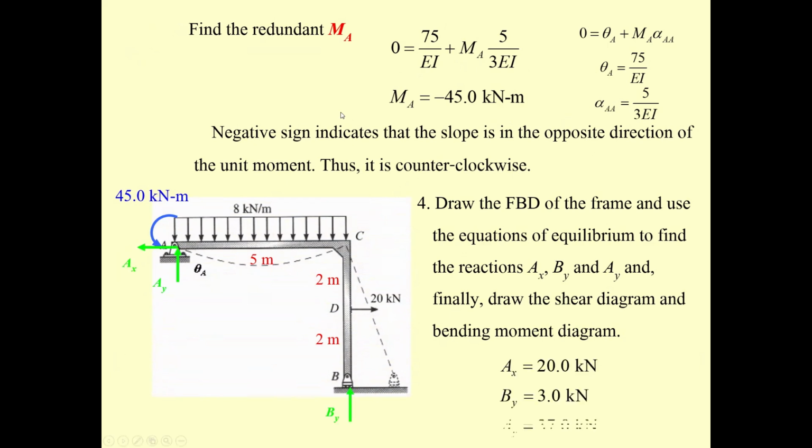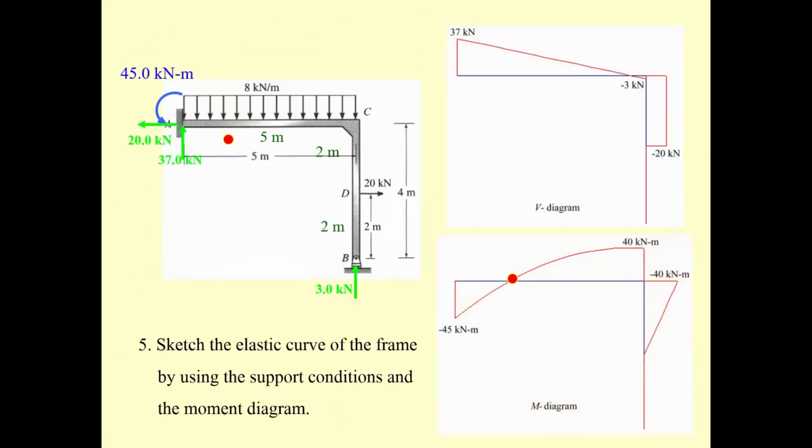And then have more examples, and I would like you to go back home and draw the elastic curve properly. And I should say, due to this portion BC, there is no moment over here, so this portion must be straight. One more thing, this is incorrect. To be correct, you want to put the roller over here.